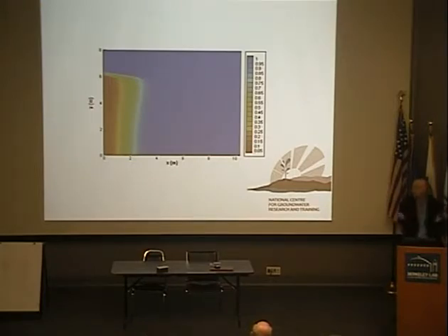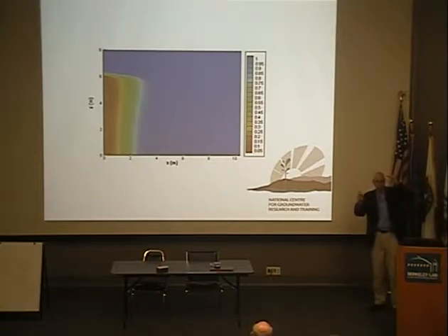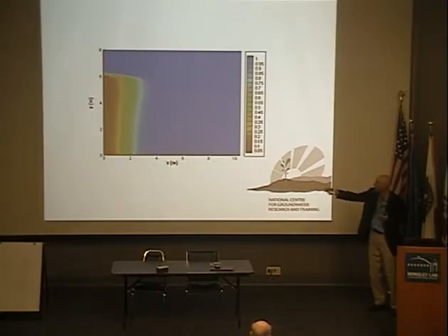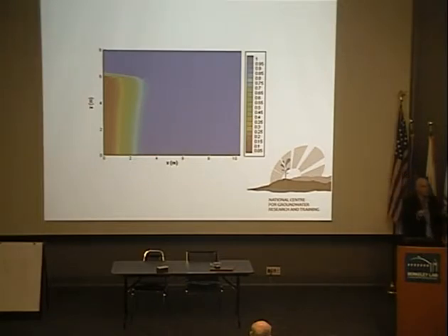We just tagged it in that way. And so you can see that the river water moves into the aquifer, in this case about 2 or 3 metres. When that flood wave disappears though, the water that discharges is not going to be groundwater; this water that's a mixture of groundwater and surface water is going to come out first.